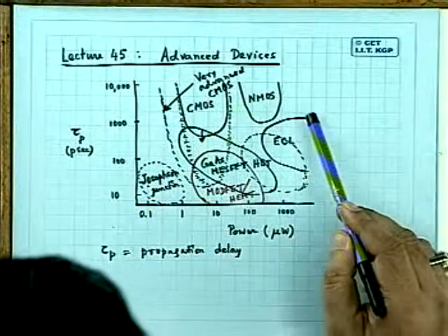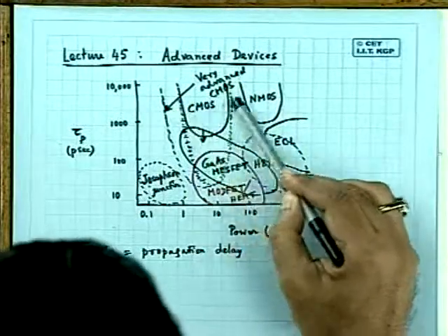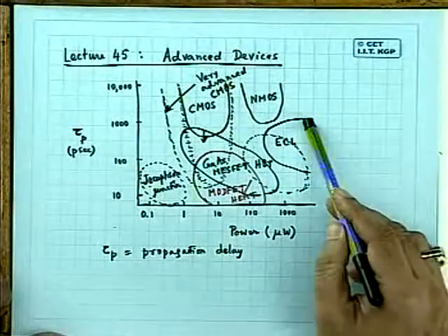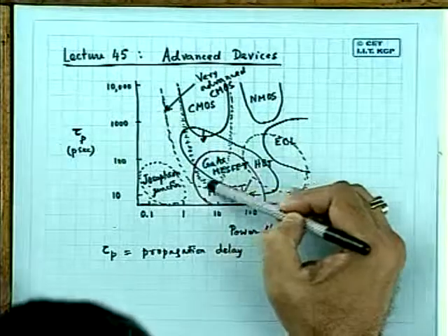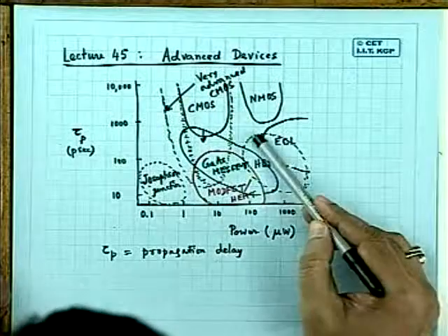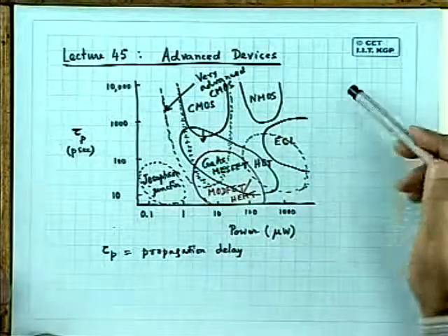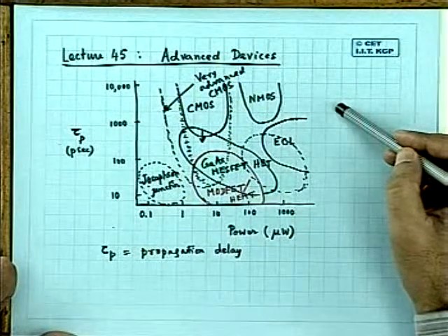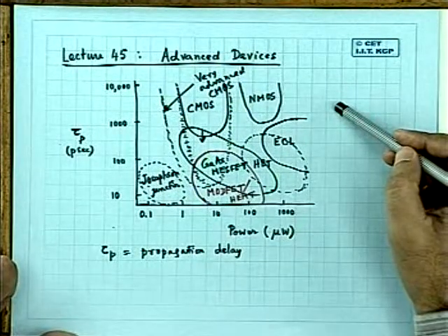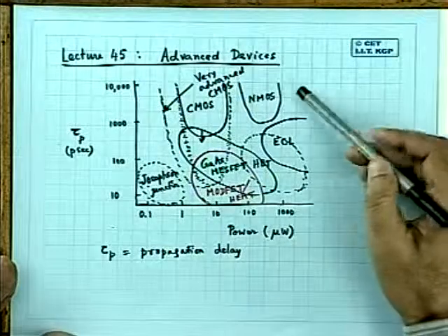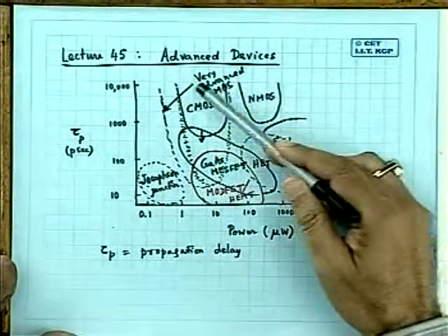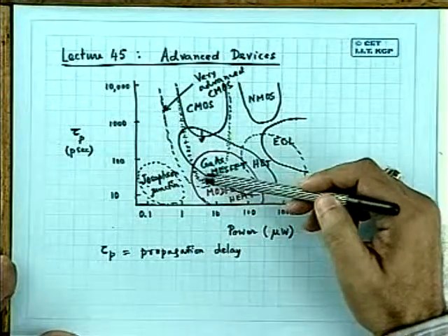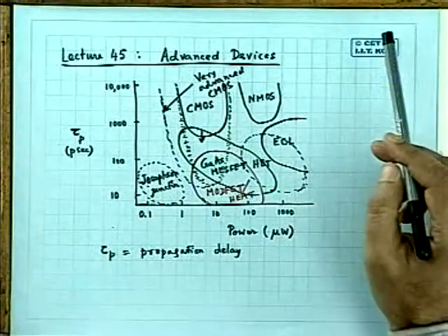So far as the black solid lines and black dashed lines are concerned, excepting this one, they were silicon technology, and they normally do not use any heterostructure. Heterojunctions are not used in NMOS technology or conventional CMOS technology which is being pursued today, excepting silicon germanium, which is a very new entrant.